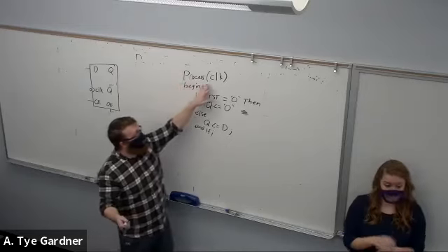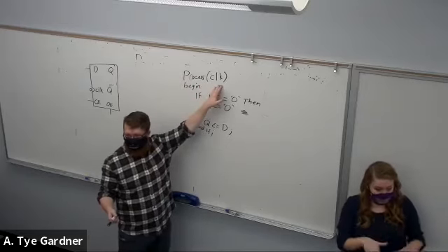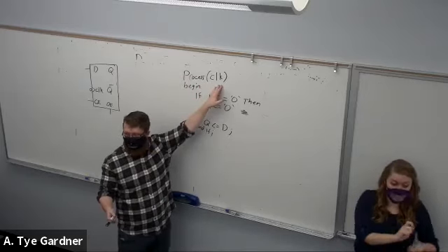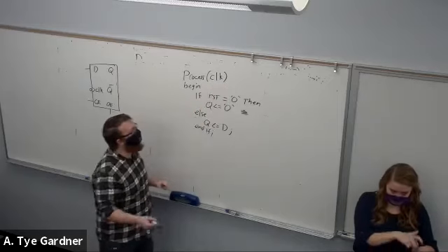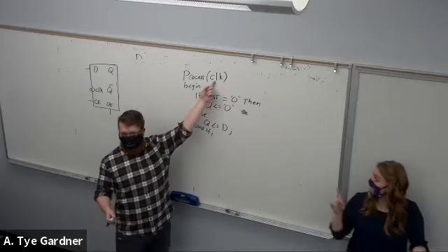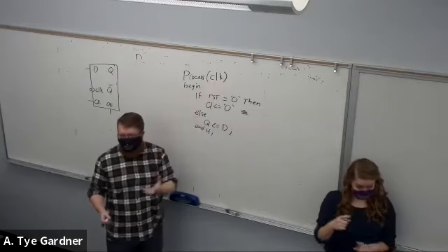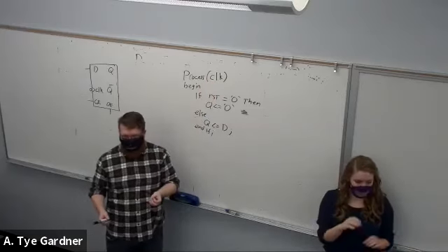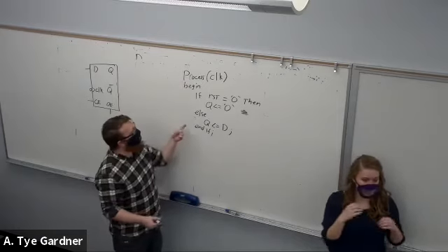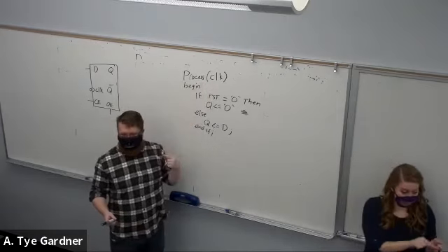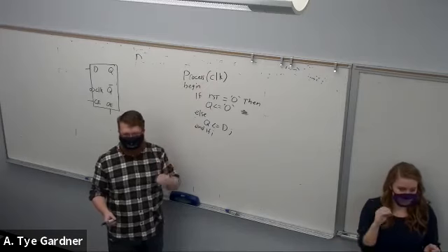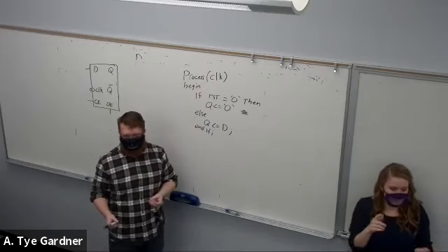Okay, so it executes when clock changes. Does it have any way of knowing what that change is, 0 to 1, or 1 to 0? Notice there's no trigger for rising edge, right? It's going to execute on a 0 to 1 or a 1 to 0. It executes whenever clock changes, regardless of direction.